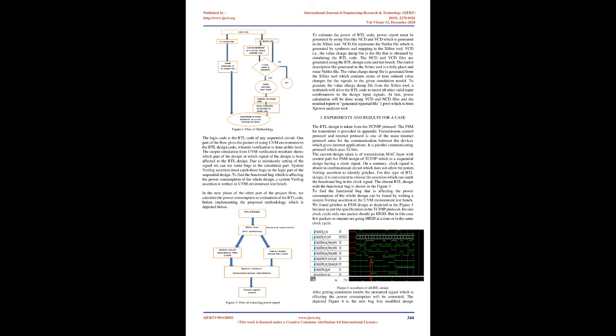Due to mistaken setting of the signal, we can see some bugs in the simulation part. System Verilog assertion must catch these bugs in the logic part of the sequential design. To find the functional bug which is affecting the power consumption of the whole design, a System Verilog assertion is written in the UVM environment test bench.